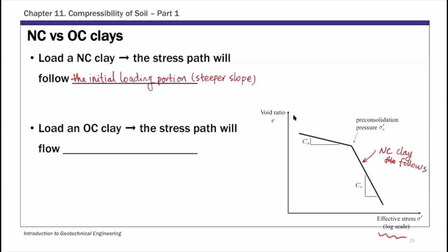For OC clay, the stress will follow the reloading. So this one has a flat slope. And the implication of this is for the same load increment, there's less void ratio change, and hence there's less settlement.